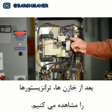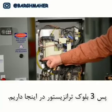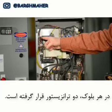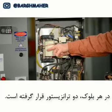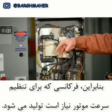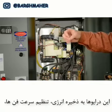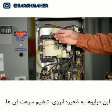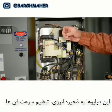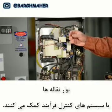Going from these capacitors over here, we have the transistors. So there are 3 transistor blocks here. In each transistor block, we have 2 transistors, and they switch on and off, and thus create a frequency that allows us to regulate the speed of the motor. This has tremendous potential for energy savings and allows us to adjust the speeds of our fans or our conveyors or our process control systems.